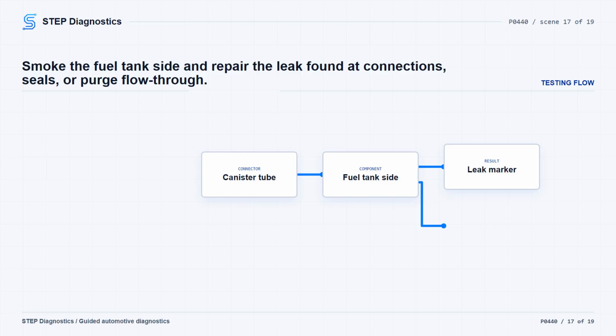You can also use a TIF 8800X combustible gas detector or equivalent, or a bubble test using an air leak detector or equivalent. Repair or replace the leaking component. If checking the purge solenoid internally, remove the manifold hose, fill the system with smoke, and if smoke comes through the purge solenoid, replace the purge solenoid. After the repair, run the intrusive leak evaluation again to verify it.